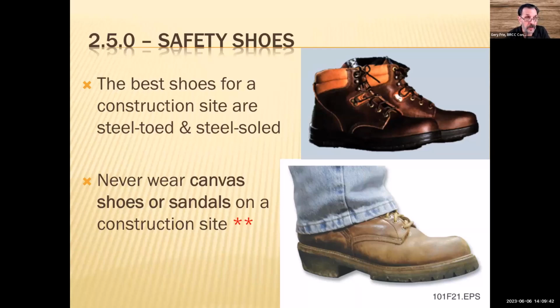A steel-soled boot or shoe actually makes it easier to stand on a ladder, by the way, because it is not so hard on the foot. If you have to stand on a step ladder for a while, a steel-soled shoe is actually a good thing. But what you see in this last bullet: never wear canvas shoes or sandals on a construction site. They're not enough protection.